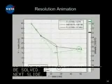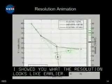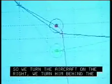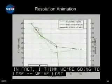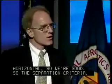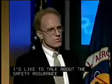So here's the resolution. Why don't you go ahead and play that? I showed you what the resolution looked like earlier. So we turn the aircraft on the right. We turn him behind the red aircraft, and you can see that we've got 9 miles, 8 miles horizontal separation. We've still got vertical separation. In fact, I think we're going to lose it. Okay, we've lost vertical, but we still have our 6 miles horizontal, so we're good. So the separation criteria, remember, is 5 miles or 1,000 feet. Okay, so what I'd like to do now is talk about the safety assurance function. Next slide. Oh, no, I'm sorry, I got ahead of myself.